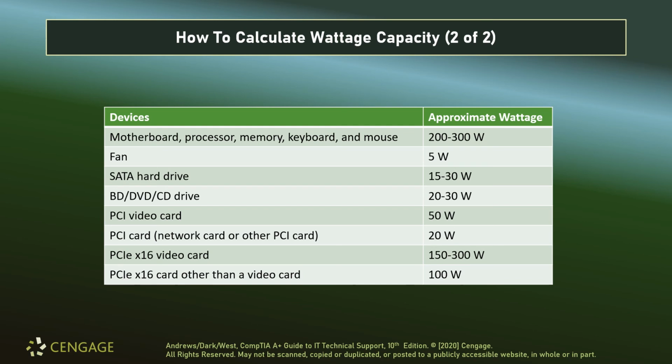If you look in your documentation for your motherboard, it may say that you have 2 X16 slots, but if you have an X16 slot that only operates as X16 by itself and when engaged will have the other one operating at X8, then that may be a limitation. So just be aware of checking your documentation first to make sure it supports the functionality that you intend, not just the wattage.